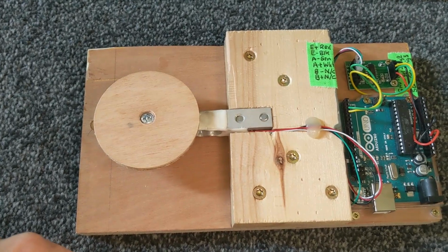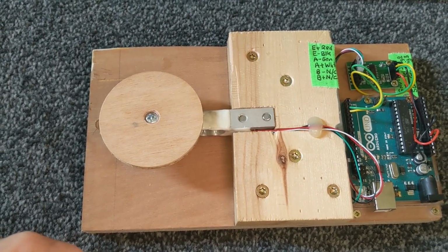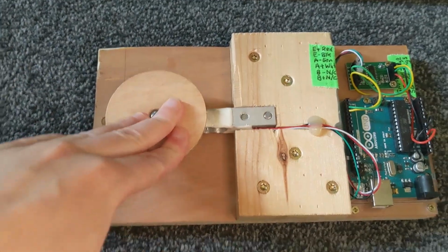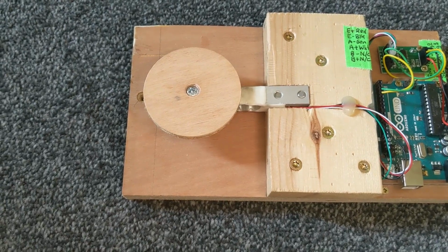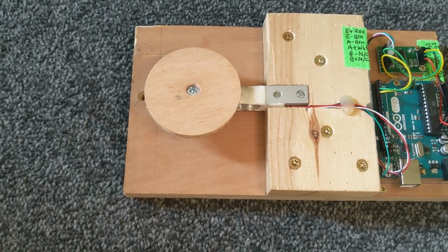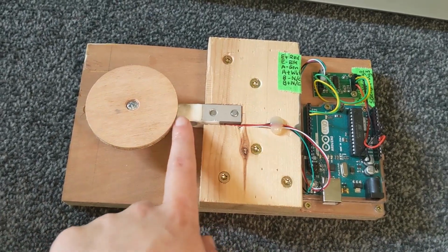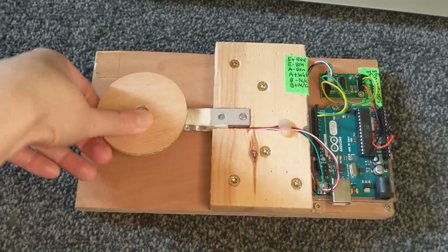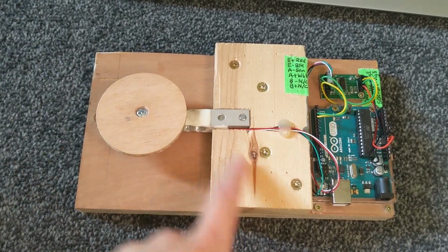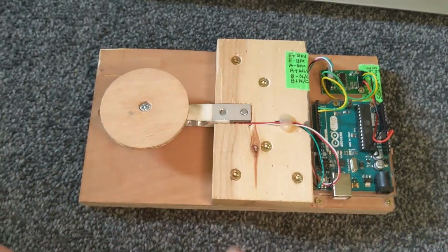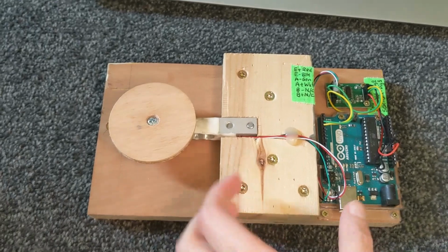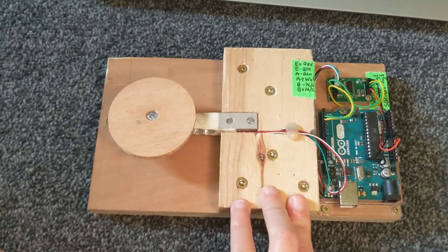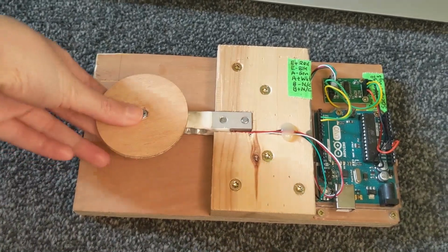So how this works, the load cell acts as a beam, and as it distorts when more weight is applied, it causes an electrical bridge circuit to change. Each section of the bank will have their own load cell and their own platform. So I know there's only one here, but imagine there would be 4 for the big thing. And again, they would be attached to this base here to hold them in place.